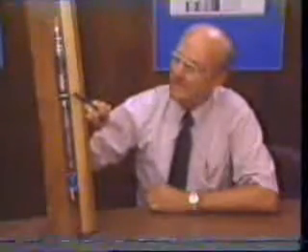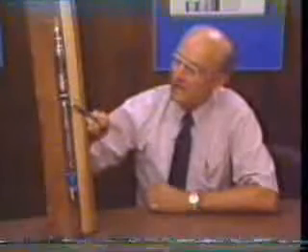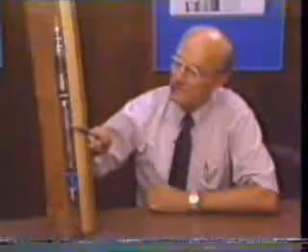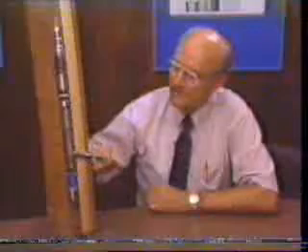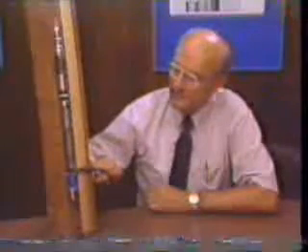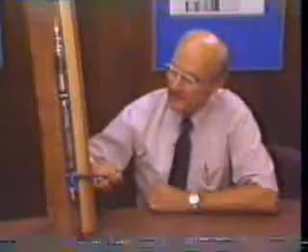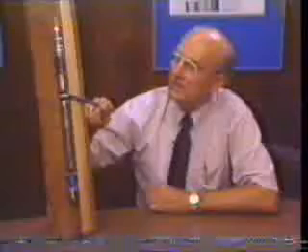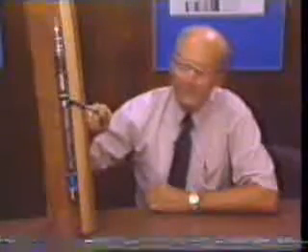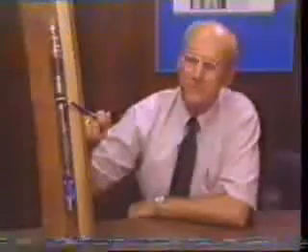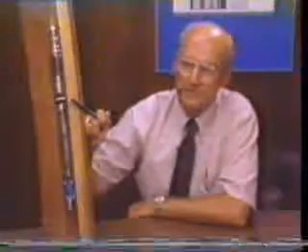This is a throttling type valve and consists of a bellows, a spring, a ball with tapered seat, and in the lower nose is a back check. The packing shown here and here isolates the casing pressure from the tubing pressure. Now let's see how this throttling valve works when it is in the well.